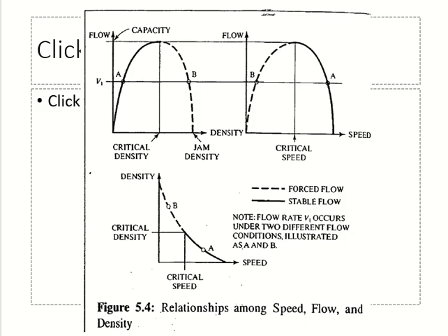What is capacity? Density or flow? Flow. Okay. So capacity of the highway is maximum flow, or rate of flow to be more precise. Capacity of the highway is maximum rate of flow. Got it? So you can reach this maximum point, and after this, the increase in density will not increase flow, it will decrease it. Got it? Clear? Any questions?